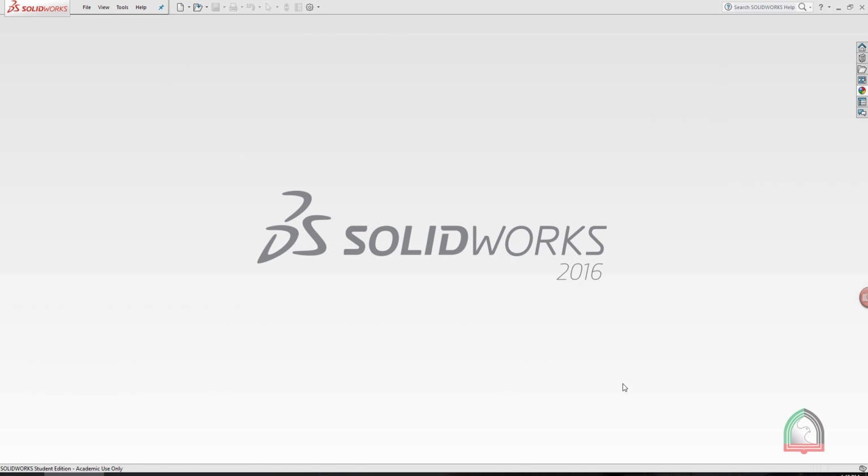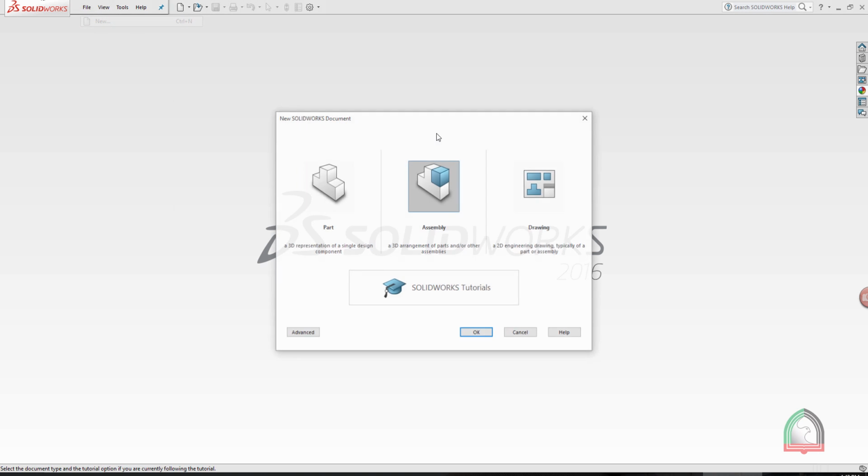So next is control handle assembly, which is a very simple assembly. Here we can see the easy use of slot mate in the mechanical mate section, and also we can compare the regular method of giving an angle limit with the slot mate, and we can also identify how much time we can save by using the right proper mate option. Okay, we'll straight away go for the assembly now.